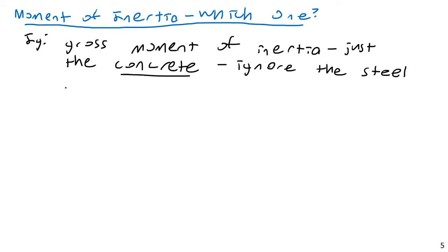And so this is basically the moment of inertia, treating the entire concrete section as if it's one uniform, nice, strong element. But we have a problem with this though. As we previously discussed when we look at the strength of concrete, we said that concrete cracks. We said that, and really this needs to happen in order for the steel to be fully engaged.